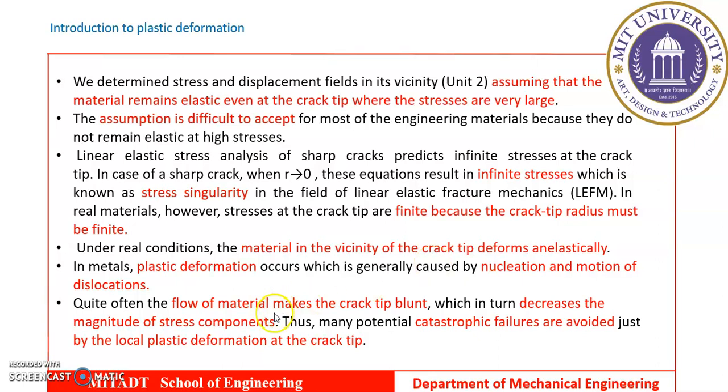Now, there is one advantage of plastic deformation near the crack tip. The flow of material near the crack tip makes the crack tip blunt. Hence the stress decreases.